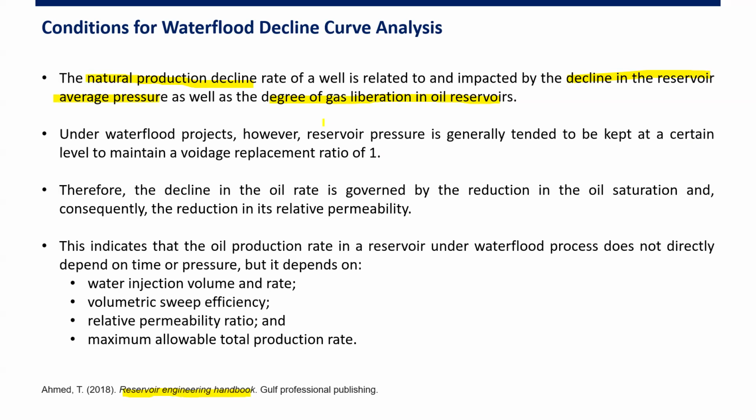However, if we now have water flood, water injection, the reservoir pressure tends to be kept at a certain level to maintain a voidage replacement ratio of 1. Right, so VRR, voidage replacement ratio of 1, is one of the main KPIs, key performance indicators, of water flood.